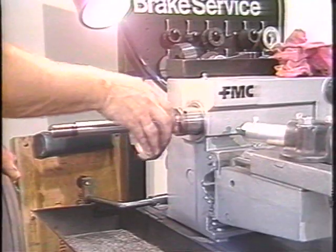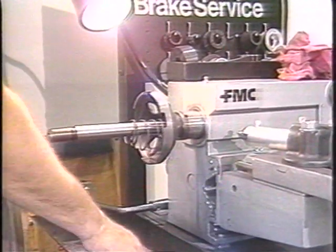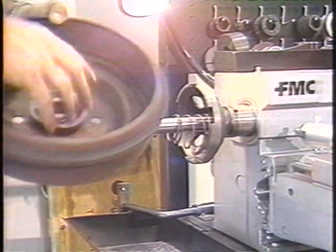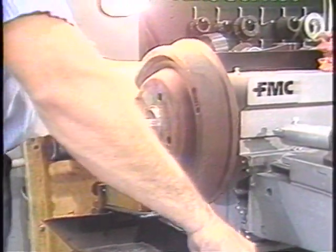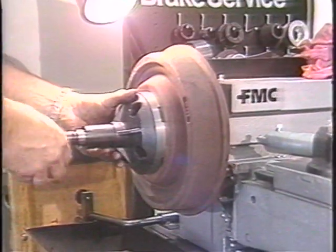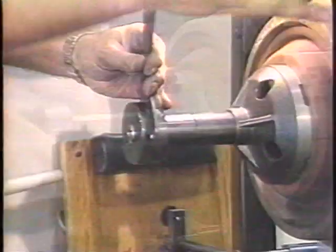Install the correct adapter on the lathe. Install the centering spring and select a cone of the correct size to fit the center hole of the drum. Place the cone and then the drum on the shaft. Place another floating drum adapter on the outside of the drum. Add spacers to fill the shaft and screw the left-hand threaded arbor nut onto the end of the shaft until snug.